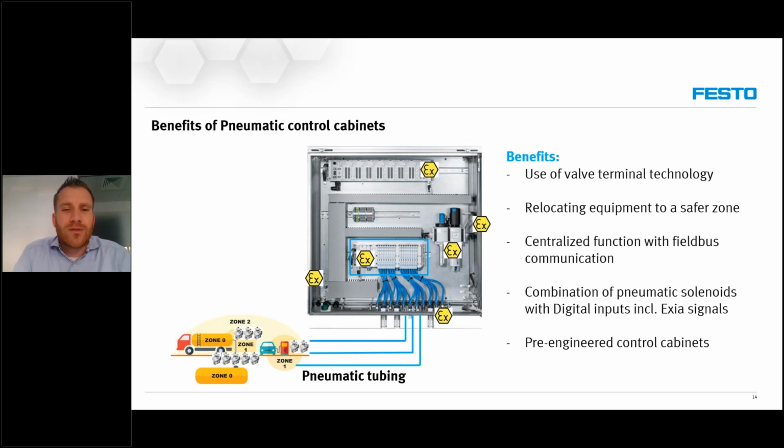Pneumatics have the benefit that they are less likely to create an explosive situation due to the low power consumption and the force of the use of compressed air compared to electric actuation. However, this doesn't mean that we can just use all the pneumatic components in a stainless steel control cabinet and expect that the solution might be safe to handle in explosive environments.